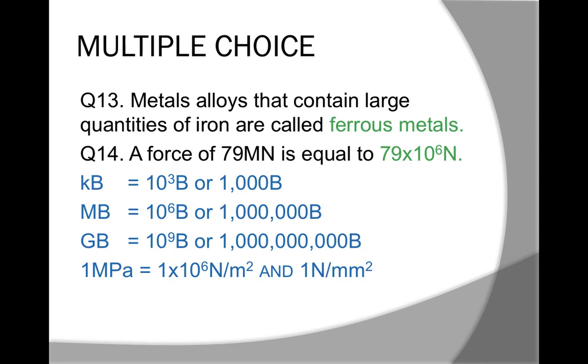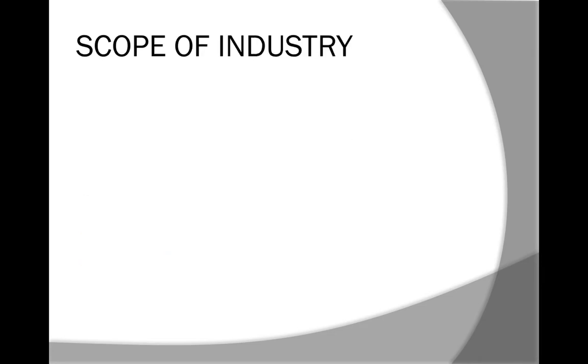We haven't covered Ohm's law. It won't be in the test for you guys, but just in case future people are listening to this. Ohm's law is, I often say V equals IR. So voltage equals current times resistance. In this case, we want to find the ohms, which is the resistance. Therefore, R equals V divided by I. So V, 12, divided by 0.8 equals 15 ohms. The symbol for ohms is omega.